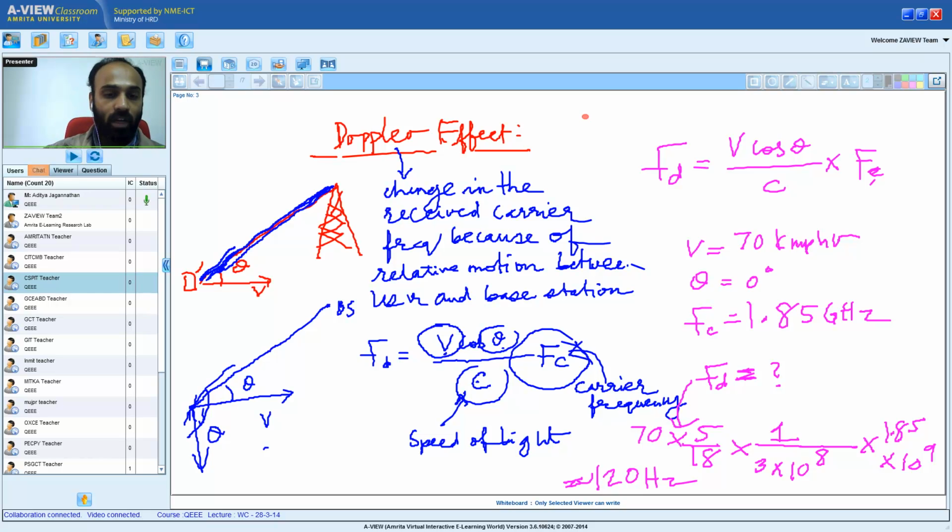For instance, we looked at antenna diversity, where you have multiple receive antennas, and we analyzed in detail the bit error rate. Then we looked at one of the most important aspects of a wireless communication system, which is the diversity order. We said that if the diversity order is L, then the bit error rate decreases as 1 over SNR to the power of L. Then we looked at the delay spread, Doppler shift, and so on.